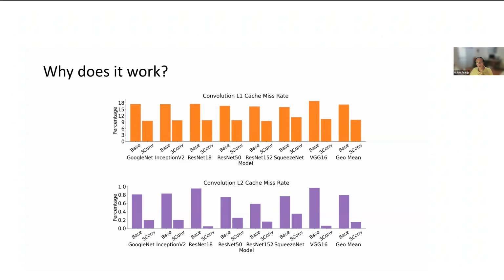This reduction in misses comes from two major sources. The tiling that we are doing, the fact that we are considering memory bursts in our exploration of the tiling space. And it also comes from the vector-based packing that we're doing, because we're not touching memory. We're doing things in vector registers, okay? So it's a considerable reduction in the L1 cache miss rate.